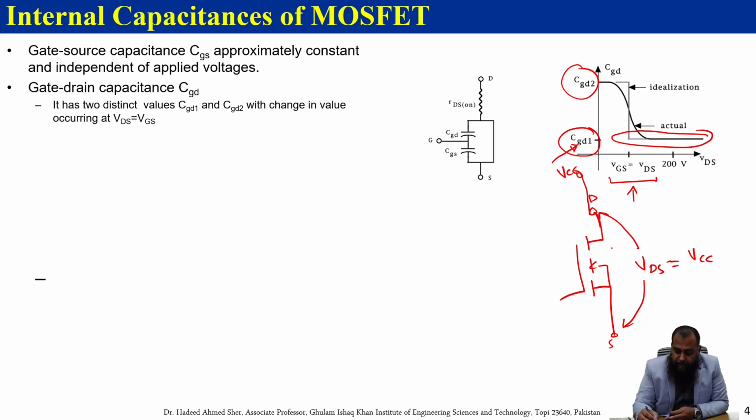However, once we try in an operation to turn on this MOSFET, once it goes into the conduction mode, the VDS will slowly go to a point where it will act as a short circuit, whereas the current IDS will begin to rise here.